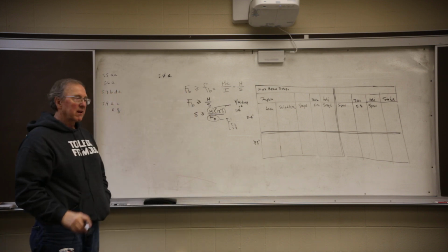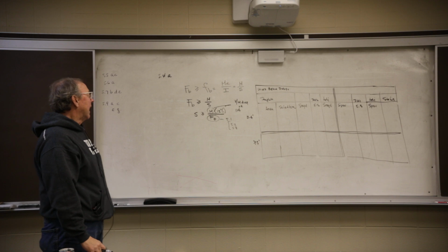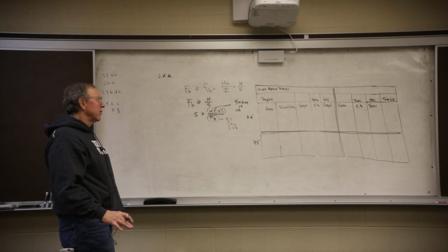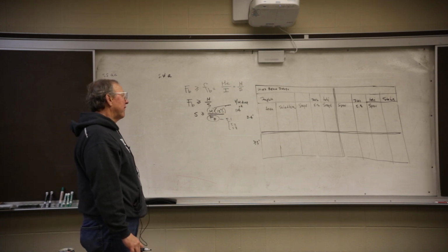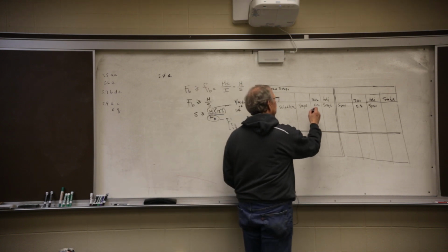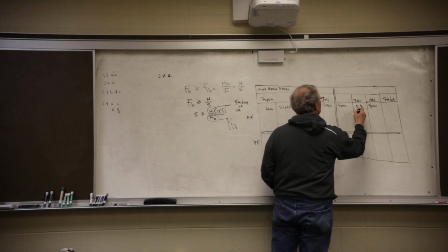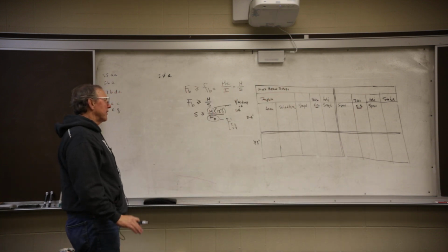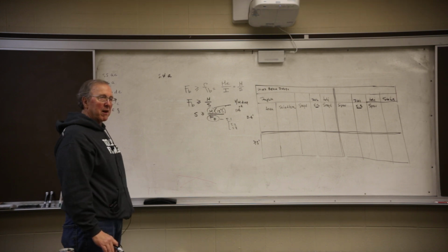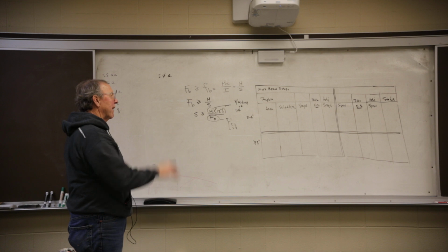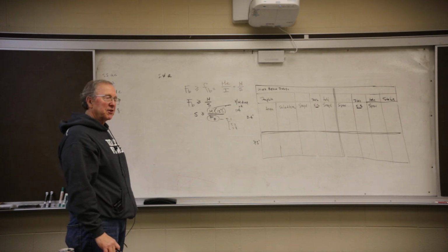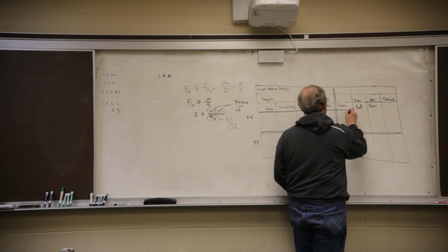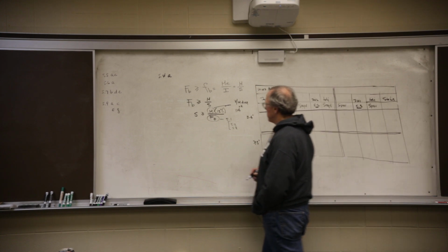So you're going to get the bending stress out of the table 5.1, and then you're going to adjust it. And you can see all you need is to get it out of table 5.1. There's the adjustment for table 5.2. There's the adjustment for table 5.8. So if you can get the right number out of the table, you aren't going to have to worry about adjusting it yourself. You just put the value into the table. The table will take care of the adjustment. Okay? So this table is going to do the work for you if you use it right. If you don't use it right, you probably got a problem.